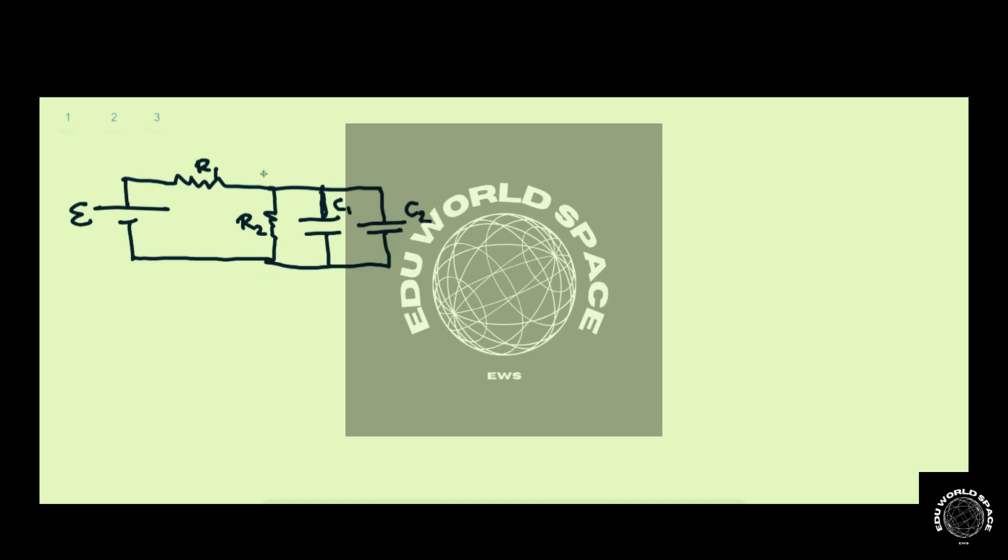We keep in mind that the capacitors are fully charged, and when they're fully charged, no current will flow through this segment of the circuit that has the capacitors. So basically we have a circuit where a current is flowing this way between the two resistors. Then we can write that E is equal to I, the current, times R1 plus R2.